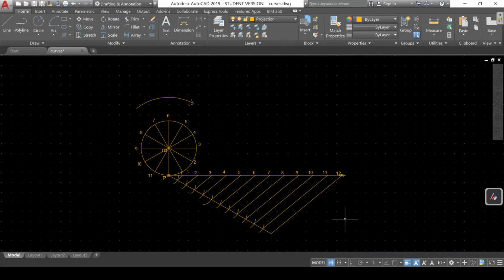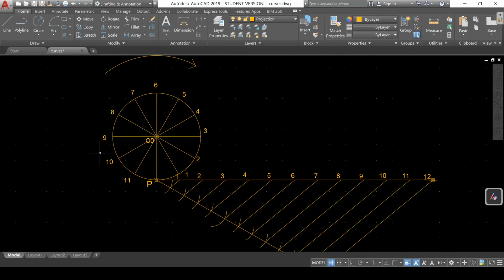So now we have got these divisions of this line into 12 parts, and we have named the divisions as well. Now what will happen, see, just imagine that as this circle is rolling on this straight line, when it rolls by 1/12 of the revolution, this P will slightly advance above, and this one will come in contact with this one, first division. Then this 2 will come in the another 1/12th revolution. This 2 will touch this 2, this 3 further, 3 will touch 3, 4 will touch 4, and so on. Finally this P will touch this 12th, because 11th P is again 12th. P is the starting point and the 12th point here.